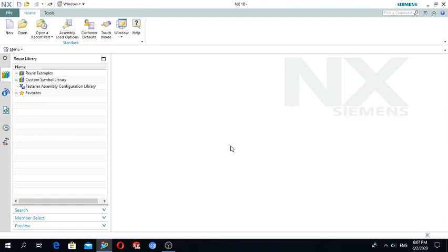In NX, you create a rough sketch and then apply the dimensions and constraints that define its shape and size. Dimensions define the length, size, and angle of the sketch element, whereas the constraints define the relation between the sketch elements. In this topic, we will learn sketching in the part and sketching in the task environment. Using the constraints, dimensions control the shape and size of the sketch. Learn sketching commands. Then learn commands and options that help you create the sketch easily.